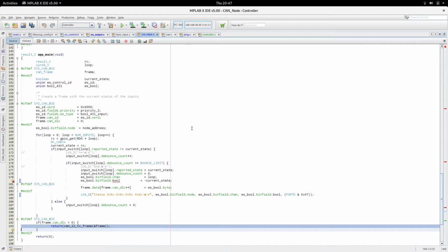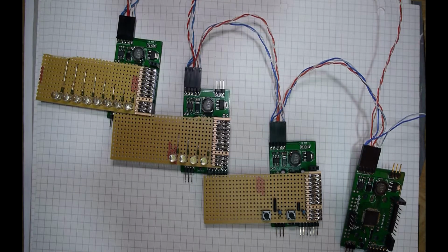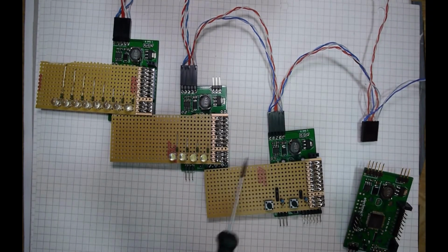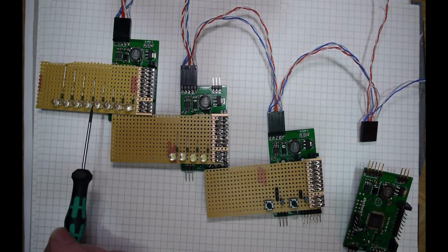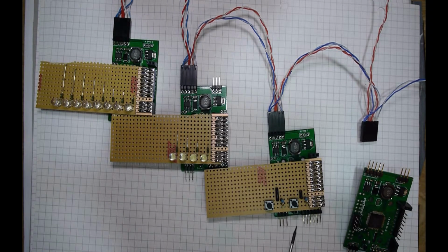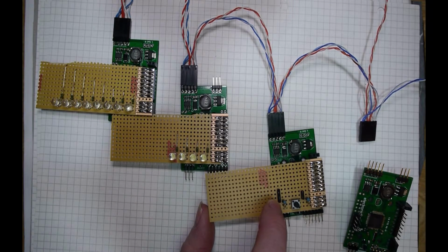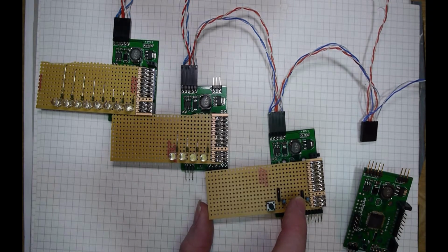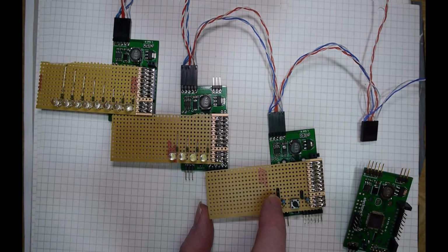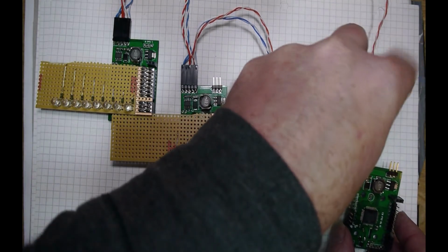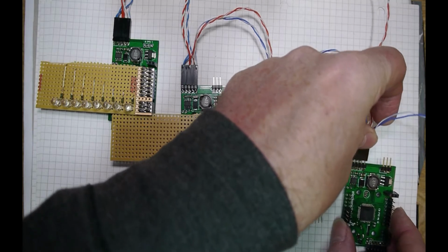And those two types of node, the input and output, if we disconnect the controller, as I call it, this is waiting for 431 output frames. This is transmitting 431 input frames. So when it transmits those frames, nothing's going to happen. So all the logic is built into this controller node.